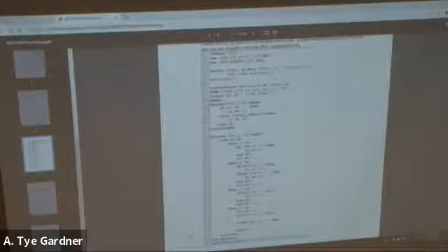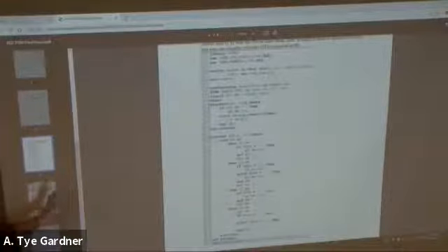What else did I say? Semicolons, returns, which is obviously right. There's no return issue in VHDL. Data types nor sensitivity lists. So you don't have to worry about converting any data types. And the way I write these, just so you guys know, is I write the code, I build a test bench, make sure it works, and then I go throw 5 things wrong with it.